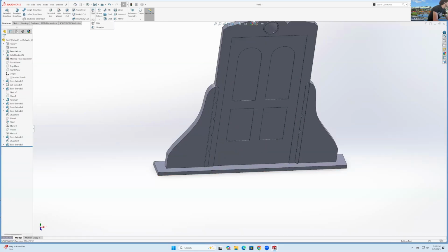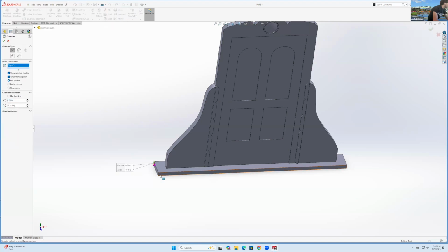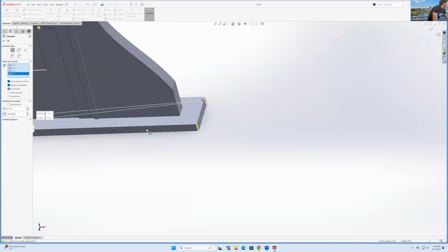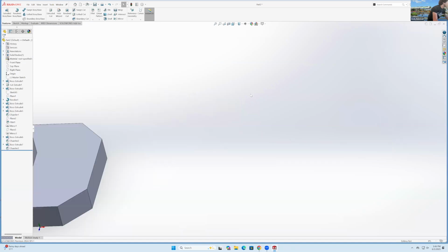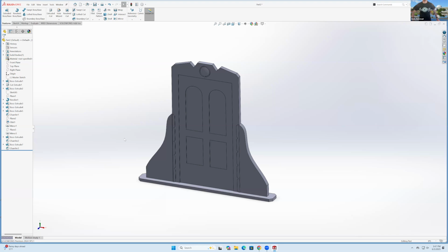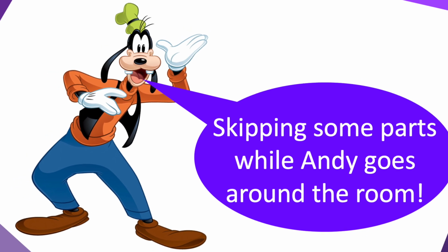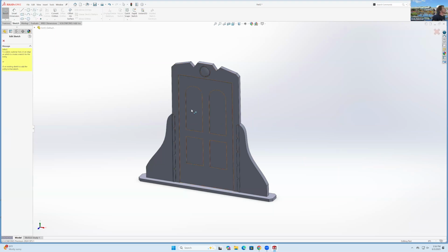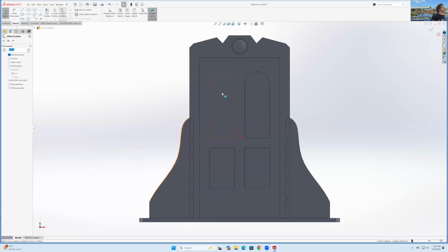And now I can just chamfer all of these edges. There we go. I'll make those 0.1. There. Now, while you guys do that, I'm gonna add details on mine in here because it's never too many details. I'm gonna offset entities reverse by 0.1.